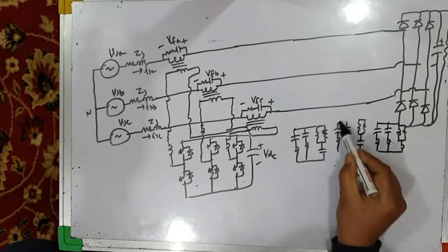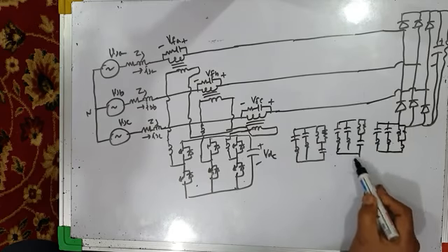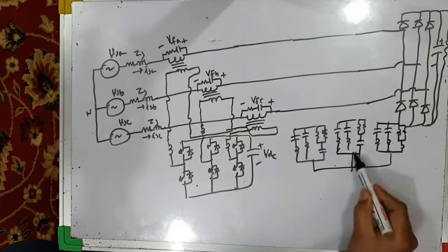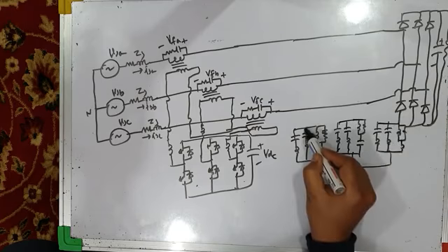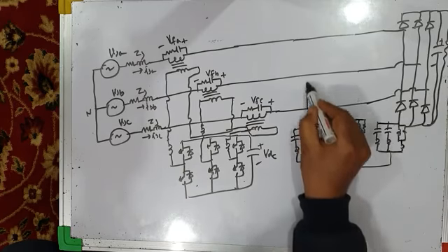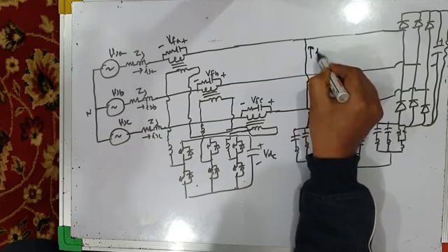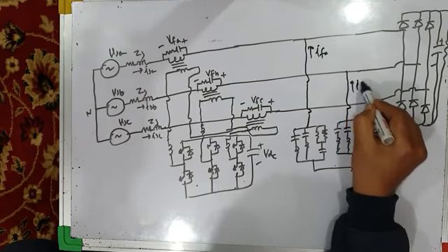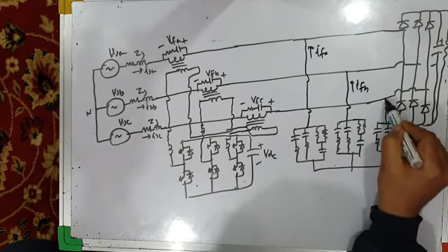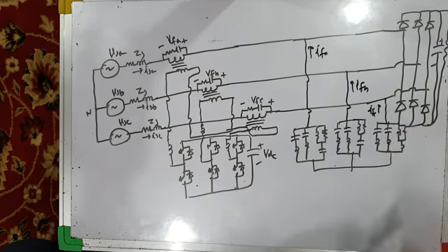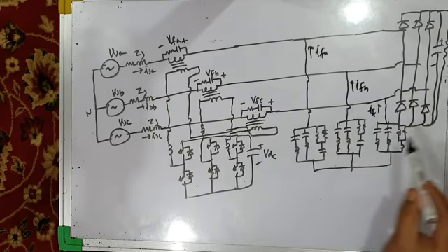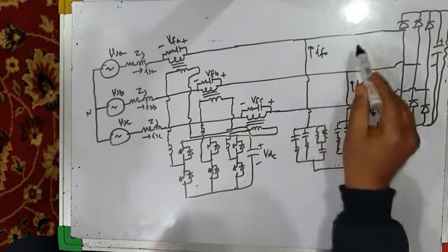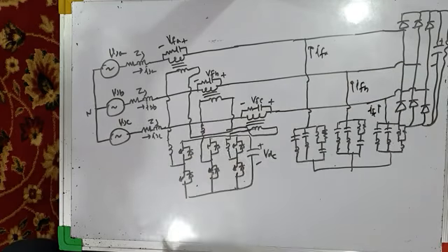And similarly here you have my passive shunt filters, star connected three-phase, three-wire passive shunt filter. This passive filter injects current IFA, this injects current IFB, and this injects current IFC. So these injected currents will cancel all the harmonics present in the load, so that source currents are purely sinusoidal.